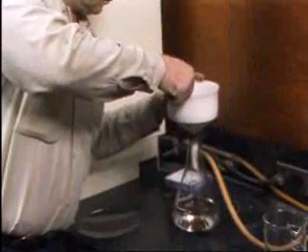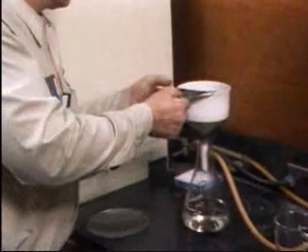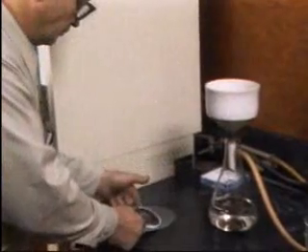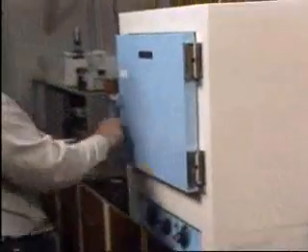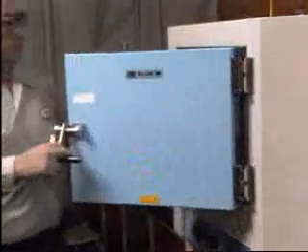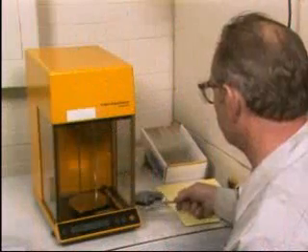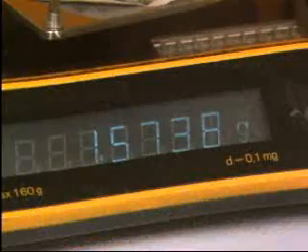The filter paper containing the solids is removed from the funnel and returned to the oven to dry. This removes moisture from the solids and the filter paper so that the actual weight of the solids can be determined. Again, plant procedures generally specify how long the filter paper and solids should be dried. After the filter paper and solids have dried for the proper amount of time, they're weighed. In this case, they weigh